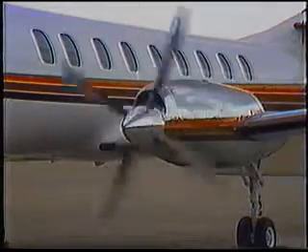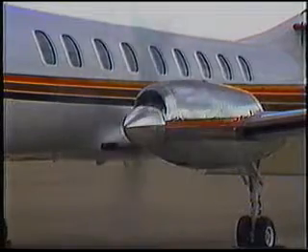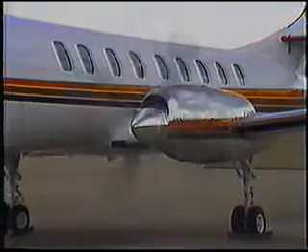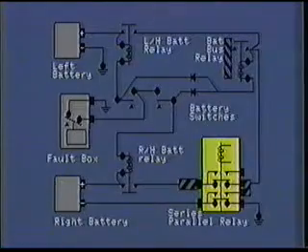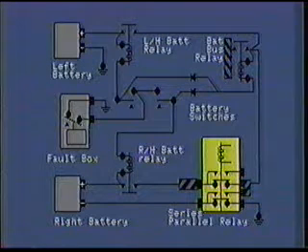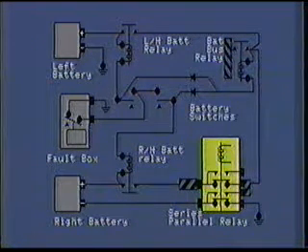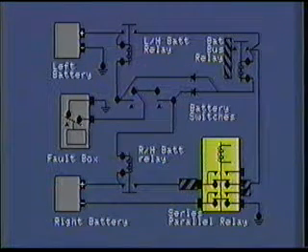During engine start, a tremendous amount of electrical power is required. If the start is being made using only the aircraft's batteries, the amount of power available may be marginal under some temperature conditions. To provide more starting power under these conditions, a circuit is installed, which, when selected by the pilot, allows the batteries to be connected in series during the engine start cycle.